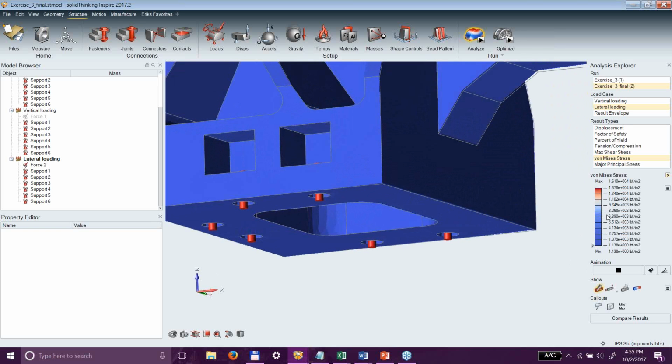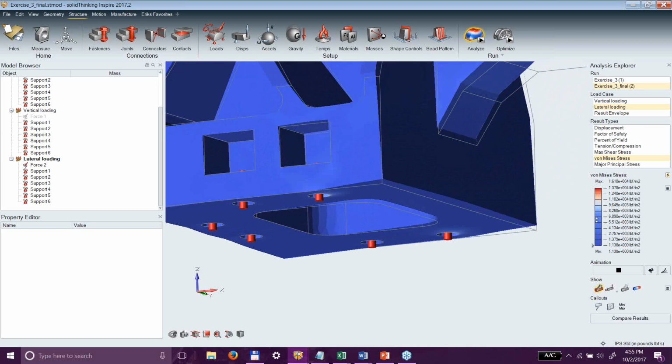Probably not. The divergent plot, on the other hand, is a 3-color plot. And aside from being rather patriotic looking, it shows me the 3 things that I'm primarily interested in. And those 3 things are what is below yield, what is at yield, and what is above yield. If it's below yield, it's blue. If it's at yield, it's white. And if it's above yield, it's red.